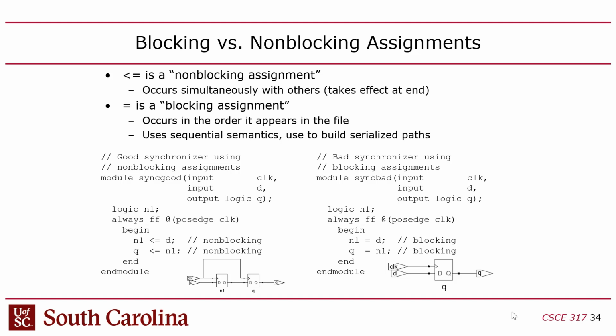So make sure you use non-blocking when you have sequential logic, clock logic, and blocking in combinational logic, and you should be fine. Now you might say, why don't they just force you to do that? Well, I think if you're an advanced SystemVerilog designer, there are cases where you would want to use blocking in sequential logic, right? But I think we don't want to do that in this class. You can get yourself in trouble if you do that, unless you know what you're doing. So it's better just to use this convention.